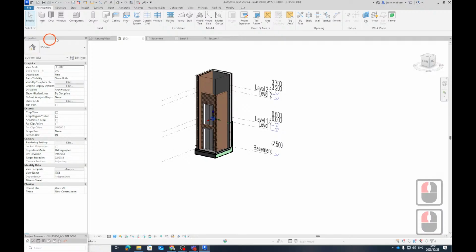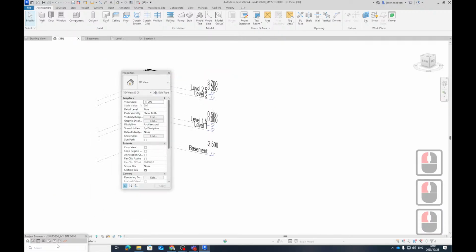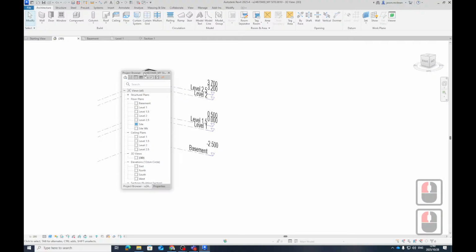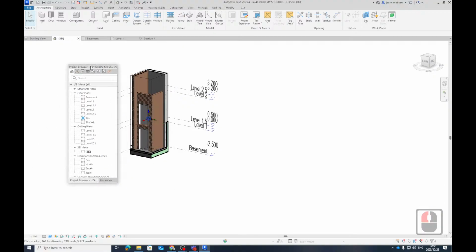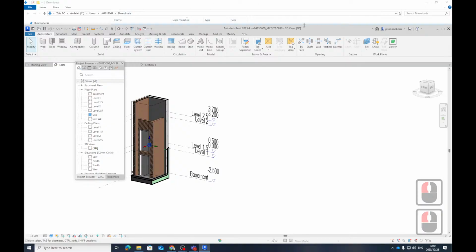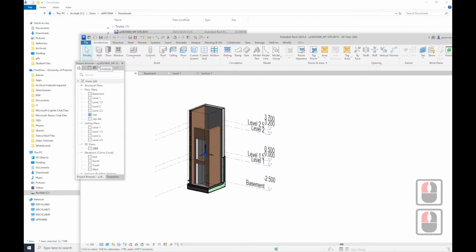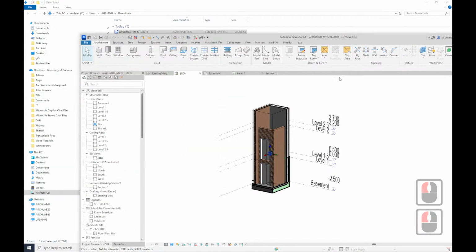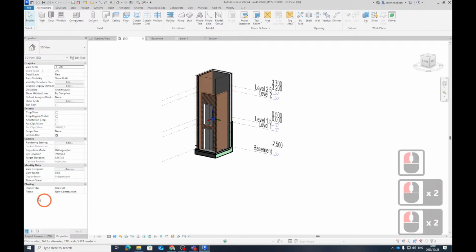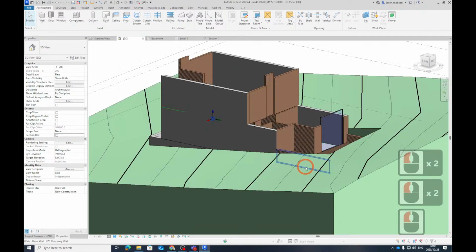Oh dear. Let me just pull this down. That happens sometimes. You want to put them in together, so tabs again, and then you drag it back to the side here again. Sometimes you've got to minimize this. I was a bit fast on my mouse there. I move this to the side, and then I drag this into the side. And it works. It's the strangest thing. Okay, so in properties, you switch off 3D section box, so it resets.